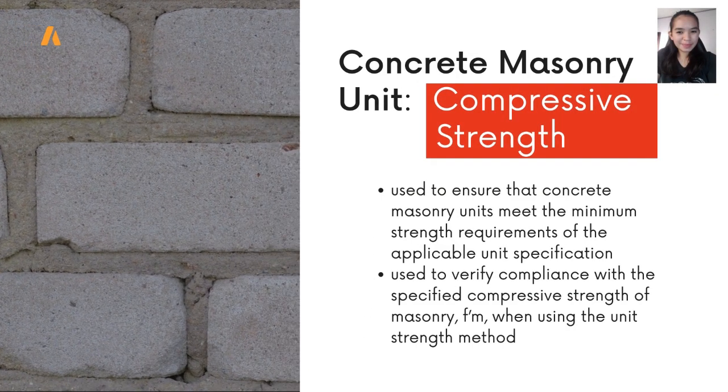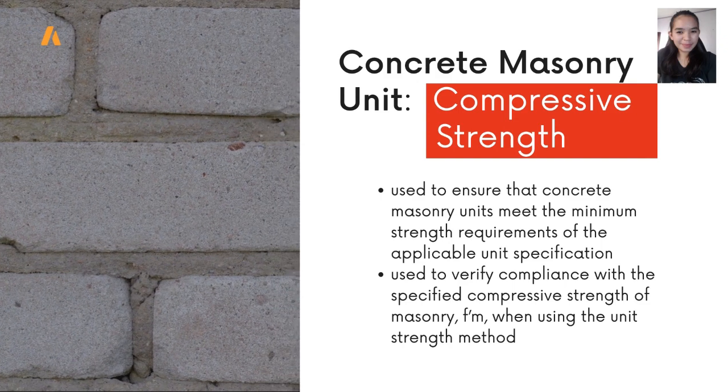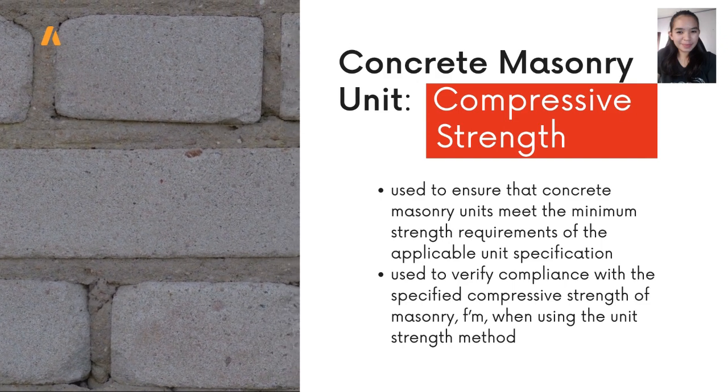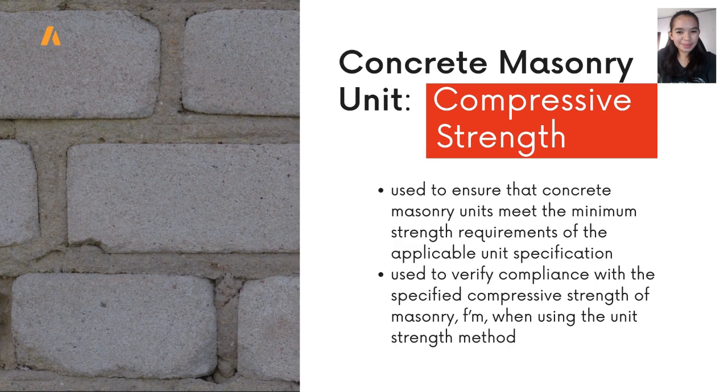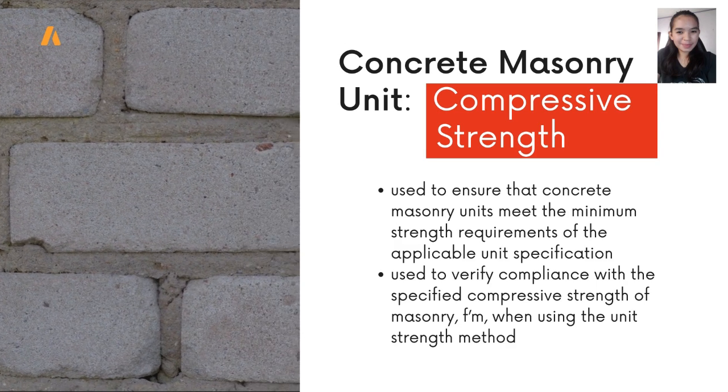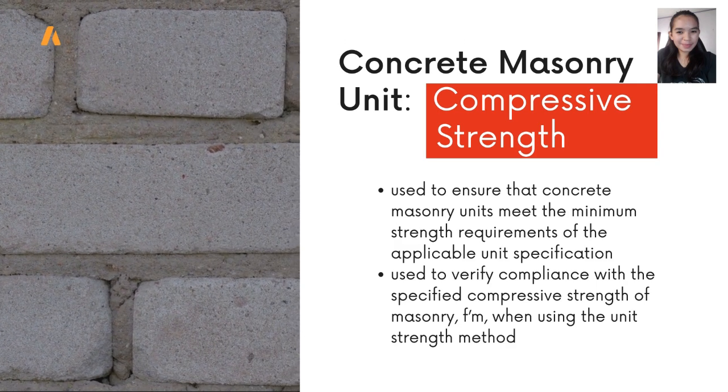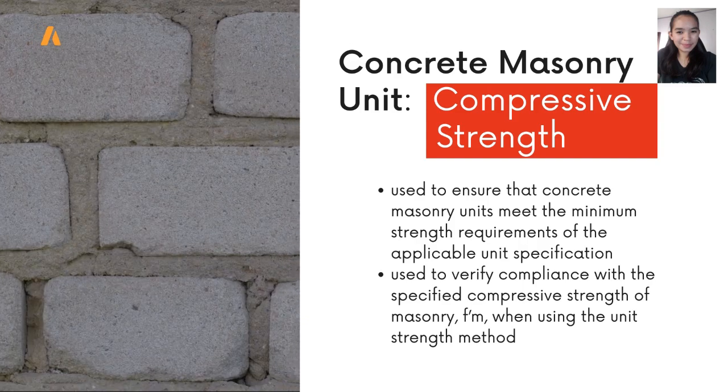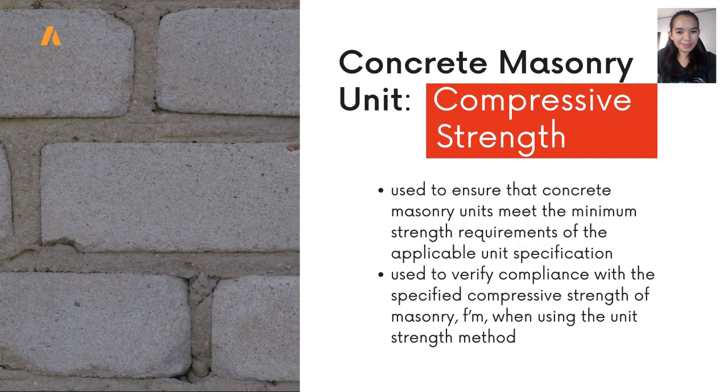Compressive strength tests are used to ensure that concrete masonry units meet the minimum strength requirements of the applicable unit specification. The unit compressive strength results may also be used to verify compliance with the specified compressive strength of masonry when using the unit strength method.